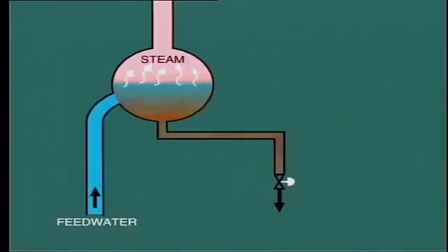Actually, the best way of keeping the solids content of boiler water at a low level is by maintaining control over boiler feed water and its makeup. The actual limits established for boiler feed water contaminants depend upon the particular boiler operating pressure and temperature and operating regime.